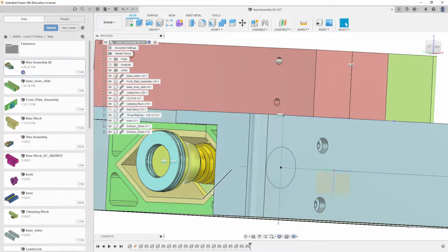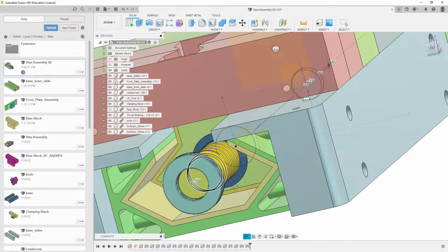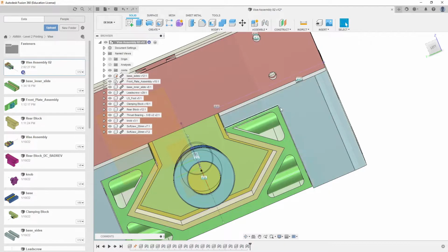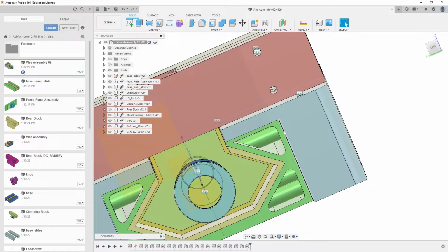We have to have that. But what hole are you using? What type of fastener are you using? And are you counterboring it, countersinking it? And the fastener length, how far does it need to go? Well, not how far does it need to go, as in we can just arbitrarily go, I guess it goes about that far. We have to know what type of fasteners are available to us.